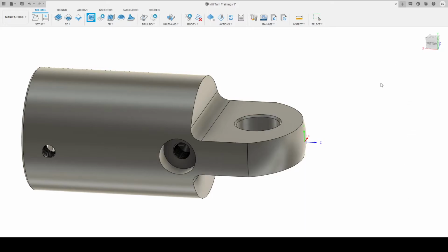So we'll select our tool. We will create a new tool. We will use a flat end mill, and we'll go to cutter. We have 4 flutes. The diameter, typically we'll use a 12mm as our go-to roughing tool. Shaft is fine. Holder, we don't typically need to model the holder. Cutting data, we will go 120 meters a minute.